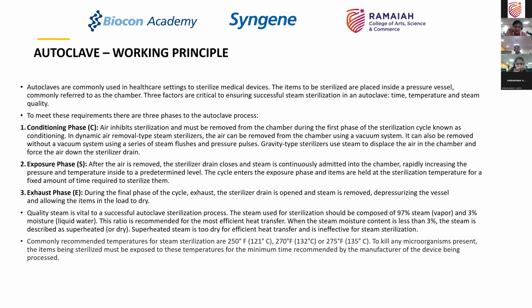So as I said, you heard me say 123 plus or minus 2, pressure range 1.3 plus or minus 0.1. So that's how you keep it. Please don't use those figures for any of your applications. It is an established parameter which is validated and then it is arrived at. So you would see that in your batch manufacturing records, or you would see that in the data in the microbiology autoclave. So you always set it up, because no equipment can maintain one constant value. There is always a tolerance.